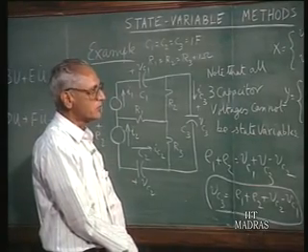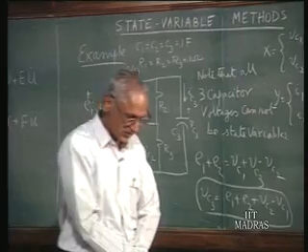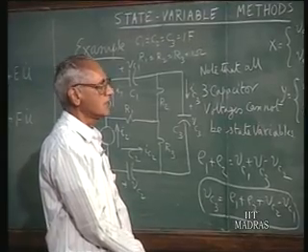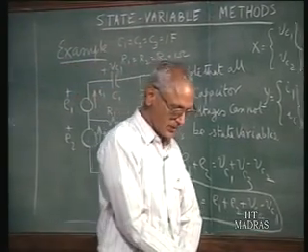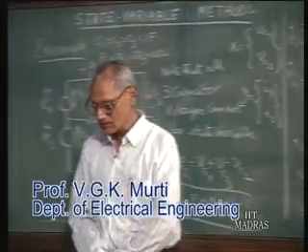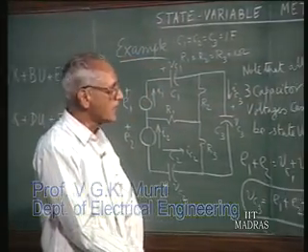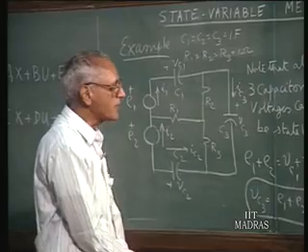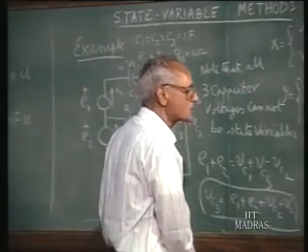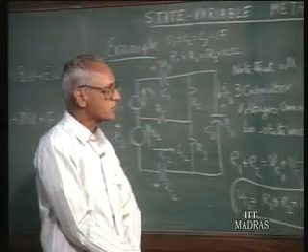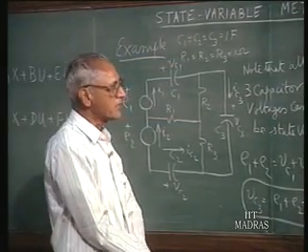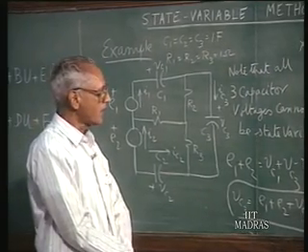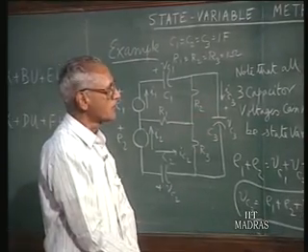Even in that case, the excess inductors can be replaced by a voltage source, and then you write the expression for the current in that excess inductor, which of course is related to the currents in the regular inductors whose currents are associated as state variables and the current source strengths, and you take the derivative of the current in the excess inductor, and that will be the voltage across the excess inductor, and that can be expressed in terms of the derivatives of the state variables, the inductor currents which are state variables, and these current sources, and following the same analysis, we will be able to write down the extended form of state and output equations wherever there are inductors and current sources forming a cut set. The whole analysis follows analogous lines to this.